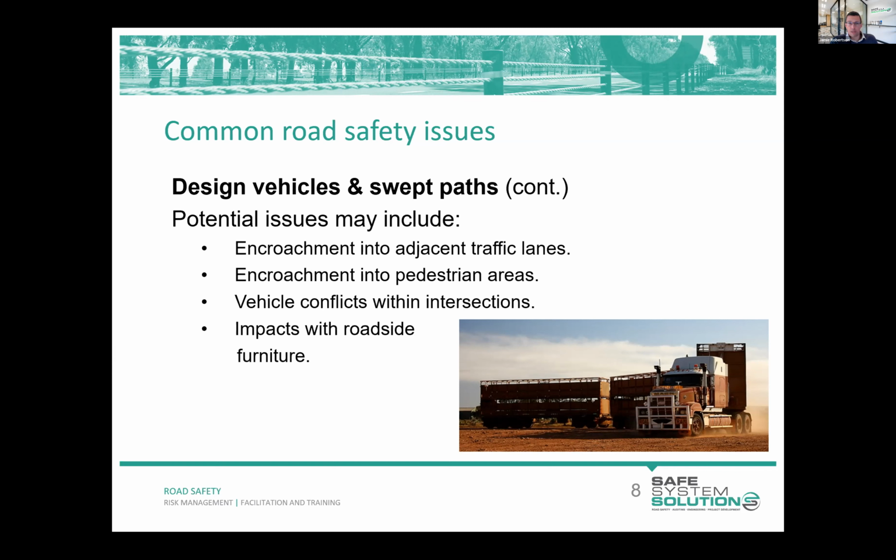You might see conflicts between vehicles within intersections. And a telltale sign of a lack of space is impacts with roadside furniture, knockdown signs and the like. Now, these are all issues with there not being enough space for vehicle swept paths.